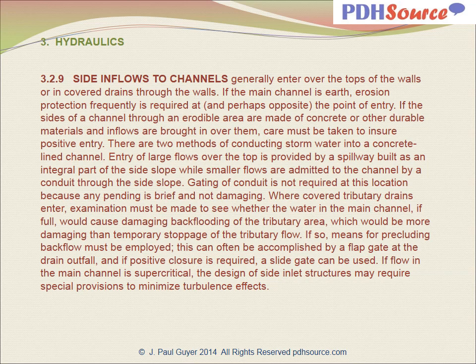Side inflows to channels generally enter over the tops of the walls or in covered drains through the walls. If the main channel is earth, erosion protection frequently is required at and perhaps opposite the point of entry. If the sides of a channel through an erodible area are made of concrete or other durable materials and inflows are brought in over them, care must be taken to ensure positive entry.